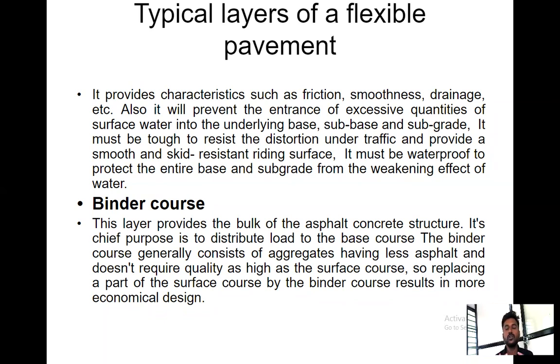You may provide that course, or you may not provide it, depending on the traffic load conditions. Whatever quality we need to achieve for the surface course, we need not go for that much quality for the binder course, as the stress induced on that layer is less compared to the surface course. So we need not achieve that much quality that is actually required in the surface course.